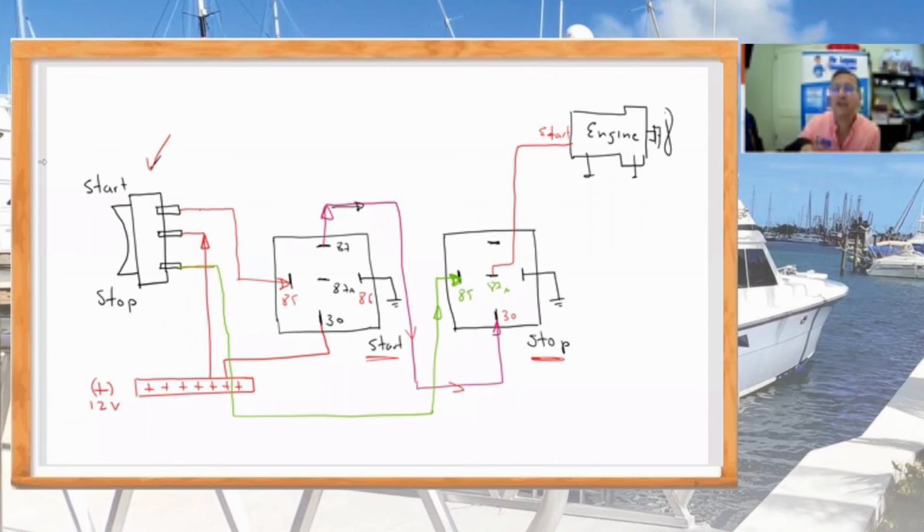My friend, I want you to keep that picture. I explained that picture when I explained the construction of the harness. You remember, on the board in the classroom? This is only that portion, only to refresh that you can combine those relays for millions of applications. Normally, the external connection between 30 and 87 is used to activate equipment, to start motors.